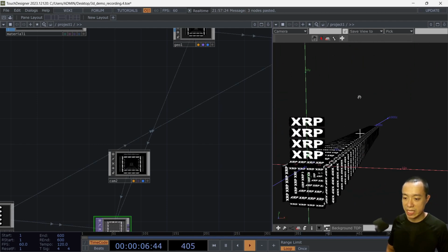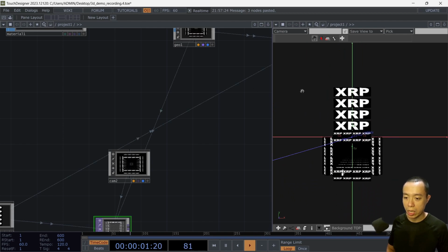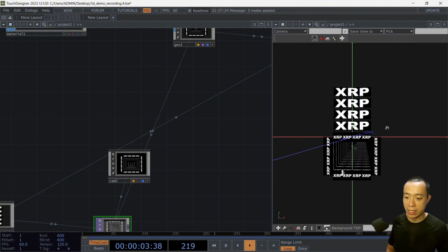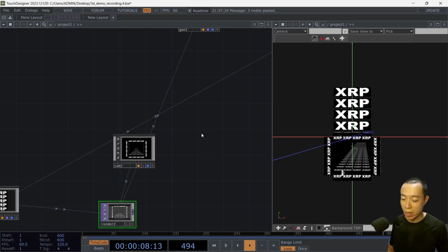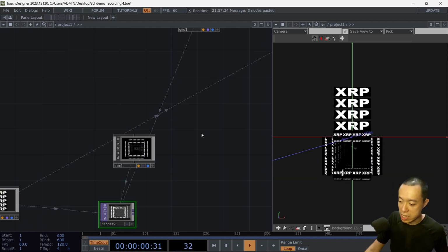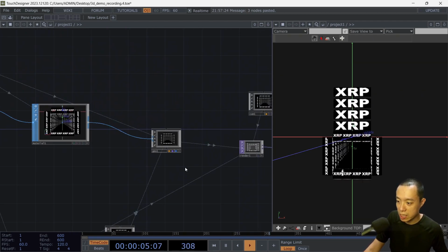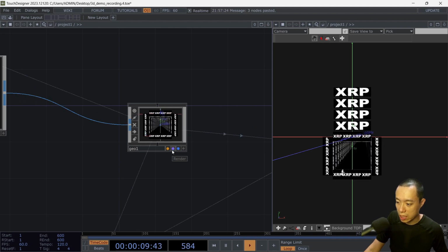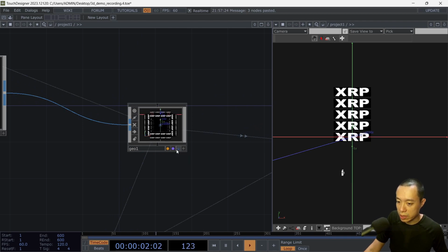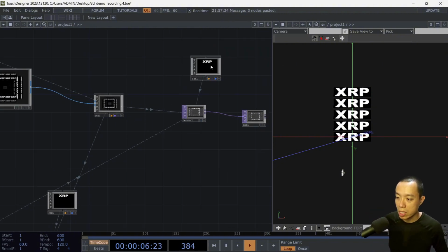Basically in TouchDesigner, if you want to hide or unhide an object without having to render it, you need to manually disable it in the geo over here. So for the geo one, I'm going to click on the display to make it disappear from the geo, and you're going to see now, even on the cam one, it sees only the geometries.